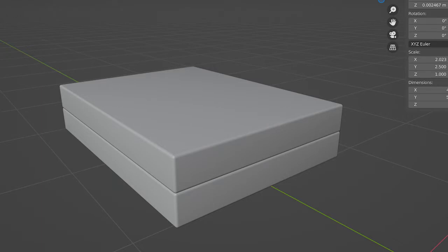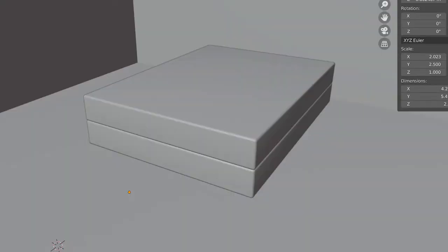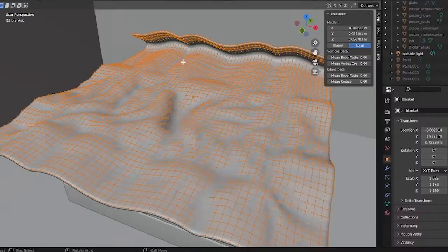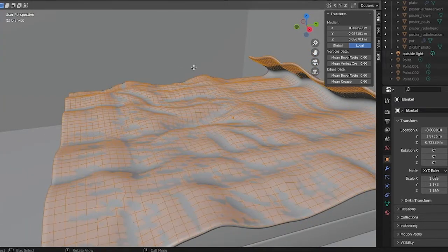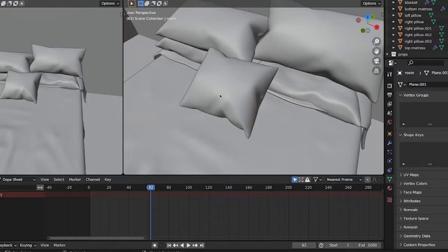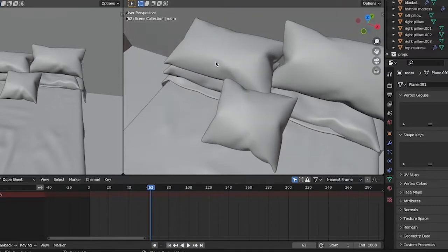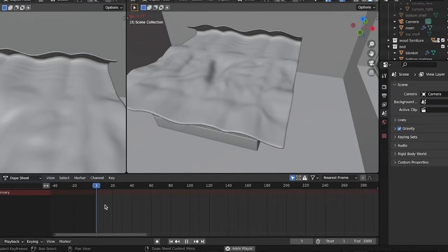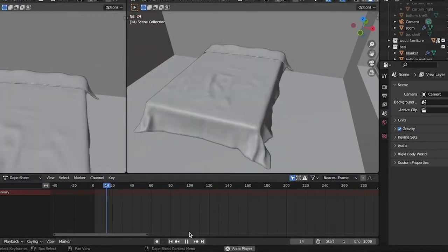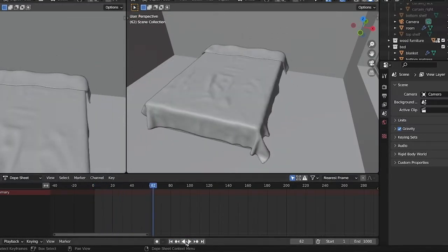To gain the correct room proportions, I used the measurements of a real queen bed in the scaling of the project's bed. Under the Physics tab, cloth simulation was used on the blanket, which was a highly subdivided plane, with various imperfections added to the mesh for a realistic appearance. The pillows also used cloth simulation with a pressure of 3 to produce an inflated look. By ensuring collisions were applied on all impacting surfaces, all simulations effectively interacted with the mattress.